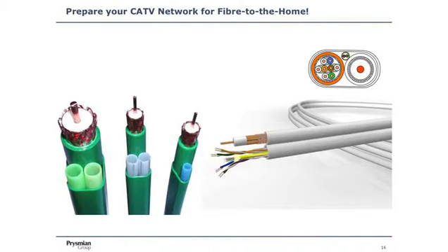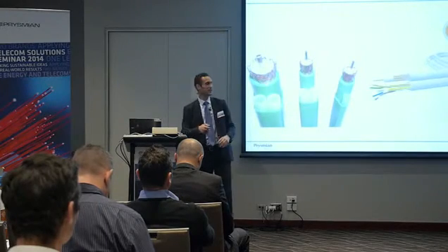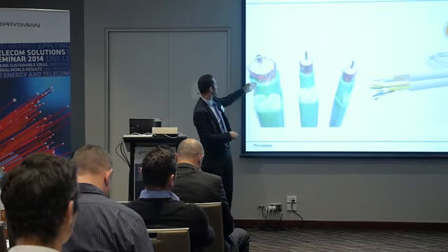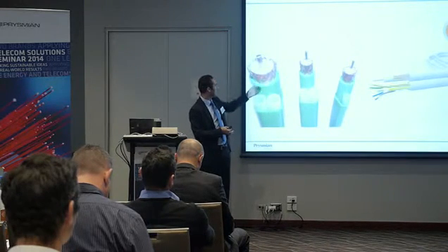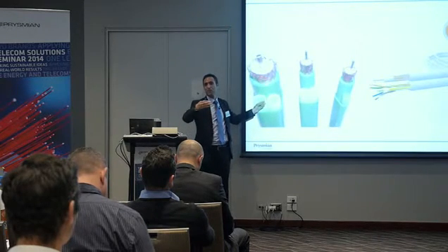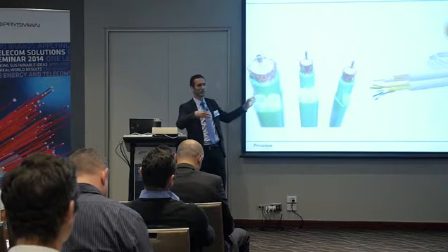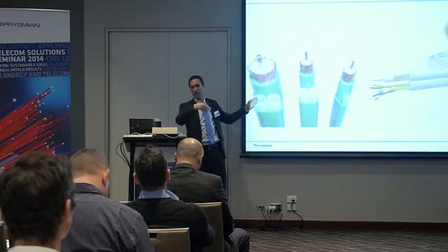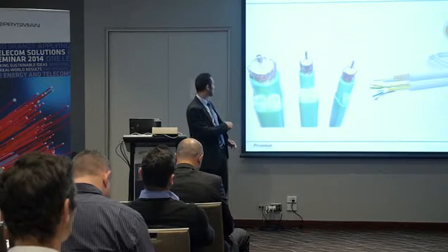Some solutions we've been proposing to couple both the coaxial trunk and the possible migration towards future optical architecture. That kind of design, for instance, where you have the coaxial cable drop, and you just deploy empty microducts, so that when you're ready, when you want to migrate your network towards fiber, hybrid fiber coax or fiber to the last amplifier, you can blow some mini cables just to upgrade your network. And we also had created some configurations with hybrid coax trunk and some DSL copper cables here.